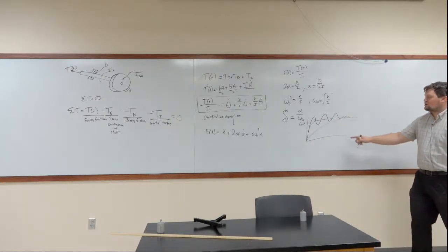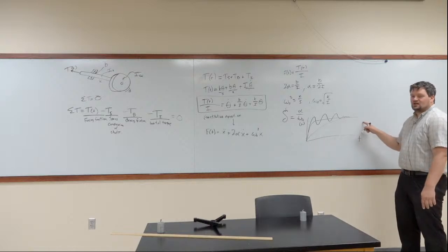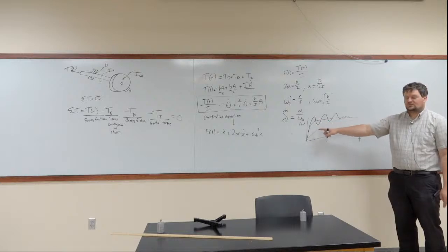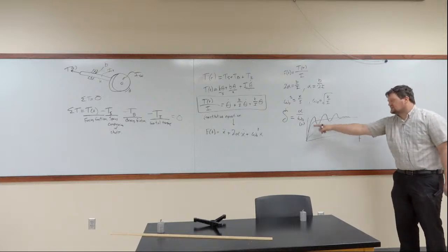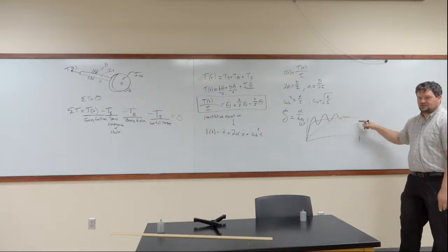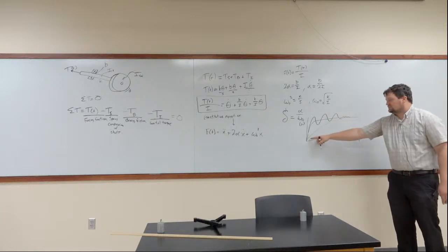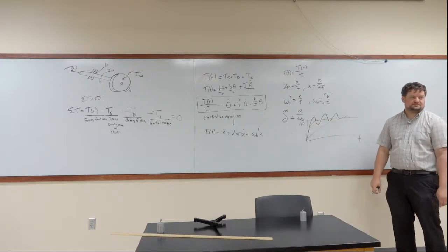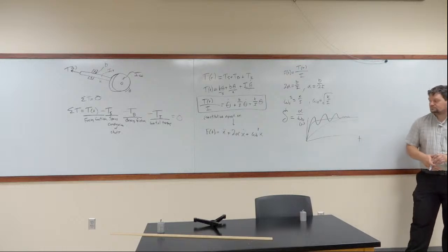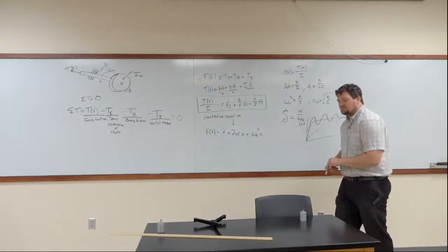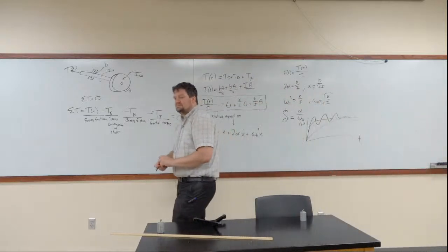So here, an overdamped system would take a lot longer to reach equilibrium, but it would not have the oscillation. An underdamped system is going to take a lot longer to reach equilibrium, but it's going to oscillate in the in-between. A critically damped system is going to reach equilibrium the fastest. I didn't talk about this last class, and I should have.